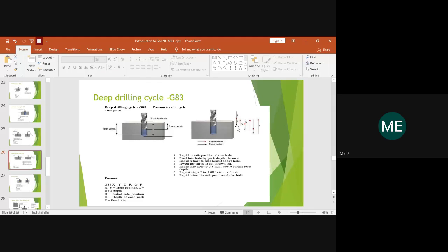So once the feed motion is given, you provide the initial safe position so that it helps the tool to bring back above the given blank. And later again you will bring the tool nearer, you will retract some material, you will provide the retract value, so it will move up, and again you provide the rapid motion, you will bring the tool nearer to the blank, and then you provide the feed, so it will provide the feed value.